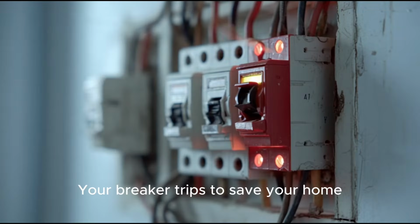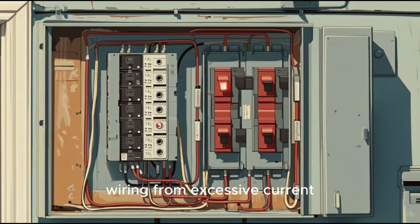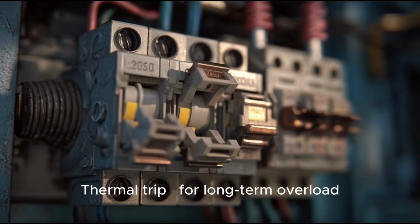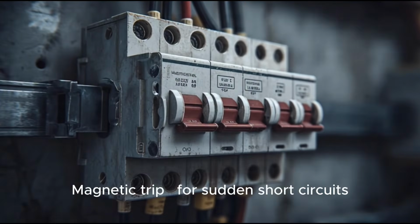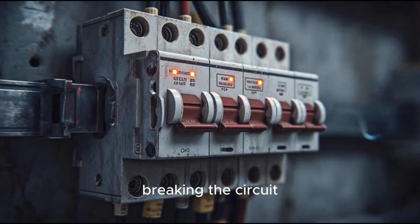Your breaker trips to save your home from a fire. Here's how. A circuit breaker protects wiring from excessive current. It has two mechanisms: thermal trip, for long-term overload, and magnetic trip, for sudden short circuits. When a fault occurs, the breaker opens instantly, breaking the circuit.